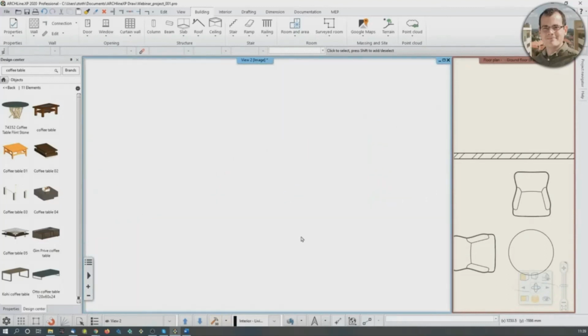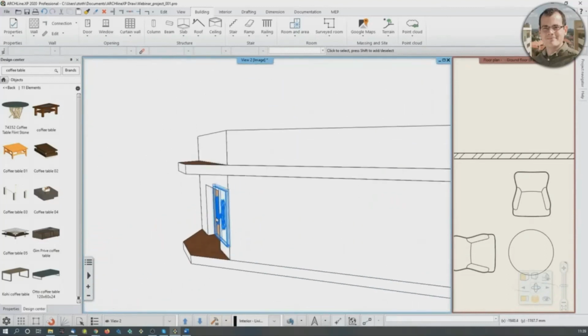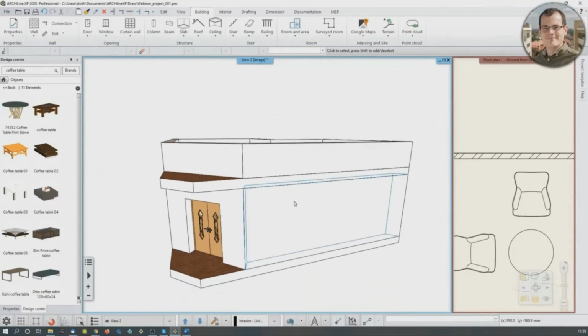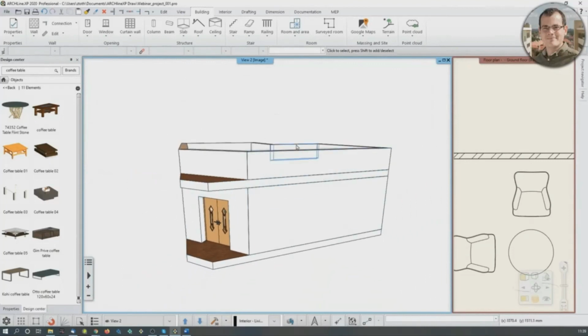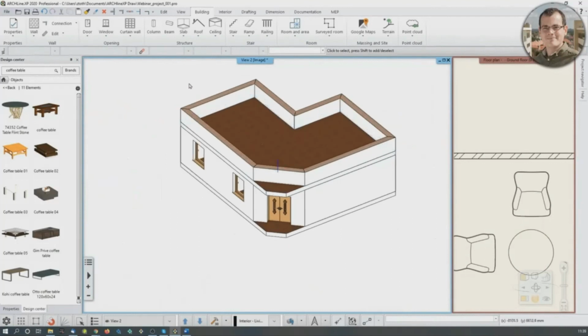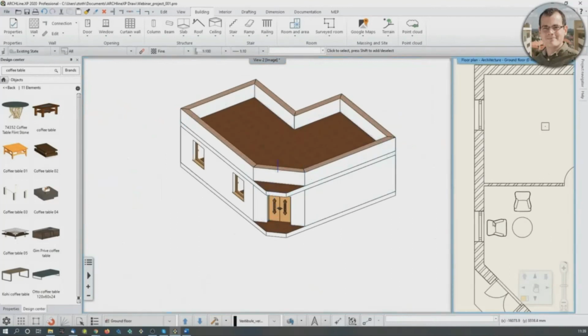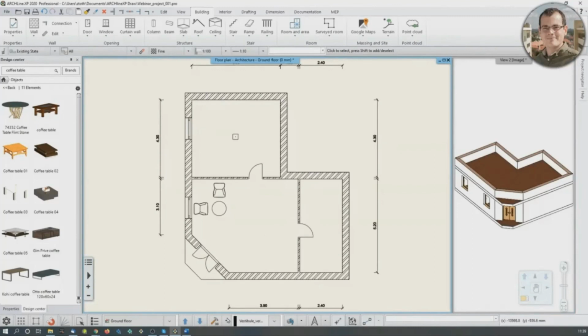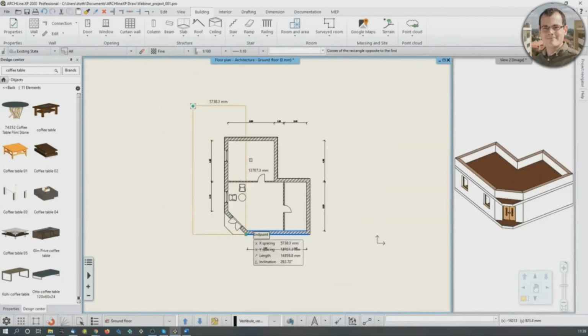There are some other things it can do on the other hand. Let's say that I want to create a cutaway model of this location. Before I do that, I click on the representation style over here and I go back to axonometry, just like that. And let's say I want to have a cut like this one. So how do I do that? I select the 2D and I click on the 3D hammer and I say create a cutaway view.